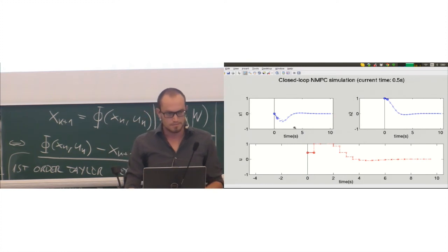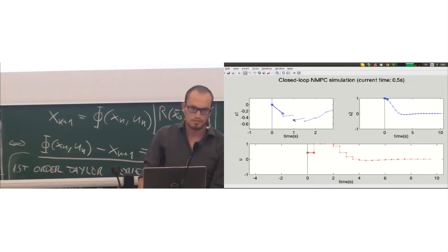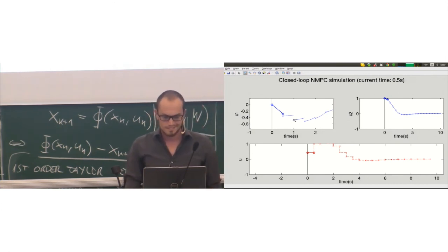But if you check the trajectories, the crosses are the points that I get out. If I use these control values to simulate from one point to the next one, I see that the simulation doesn't quite get to this next point, right? There are these gaps popping up, which is exactly what multiple shooting does. It defines that the next point is equal to calling your integrator on the previous point using the control. So these gaps are the nonlinear constraints in your NLP. And one SQP iteration is simply not enough to get completely converged, of course. That would be very nice if that was the case. So we don't have a fully feasible trajectory, but still we just apply the control input blindly. That's the idea of RTI, to just do one SQP iteration.